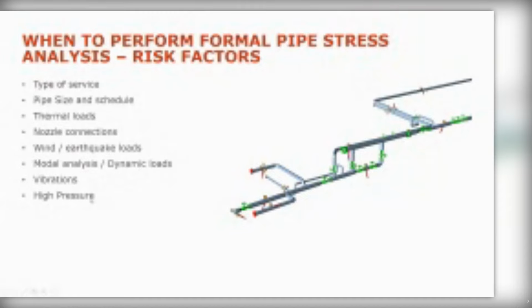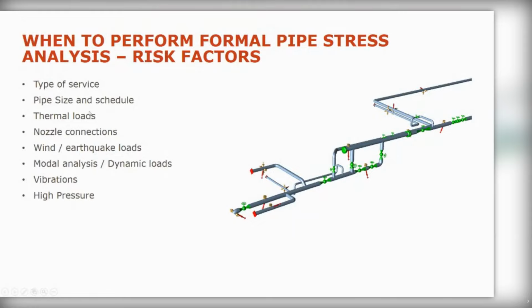If you have high pressure, possibly, I would say. If it's just pressure but nothing else is going on in the line, there's no thermal growth, it's well supported, you probably don't need it, you just make sure your pipe is thick enough. But again, like the type of service thing, if it's very high pressure, you really don't want it to fail. So it's probably prudent to do pipe stress analysis, but the big drivers are there. Now, those are the important risk factors.